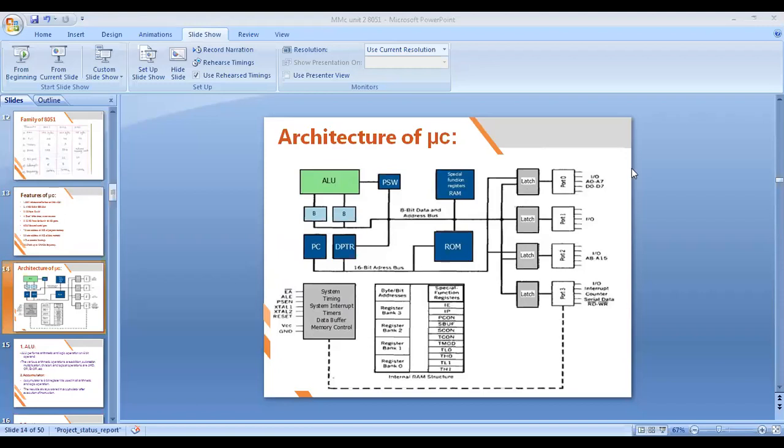Okay, now, very important, that is the PSW. See here, PSW stands for Program Status Word. It is the flag register present in the microcontroller. So what is the use of a flag register? We know the flag register, according to the result performed by the ALU, replicates that result. Depending upon the result it will make some bits set, some bits reset. So that is the same use present in the PSW.